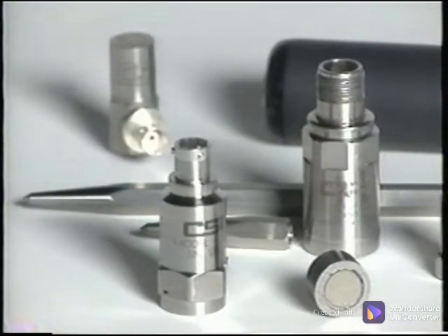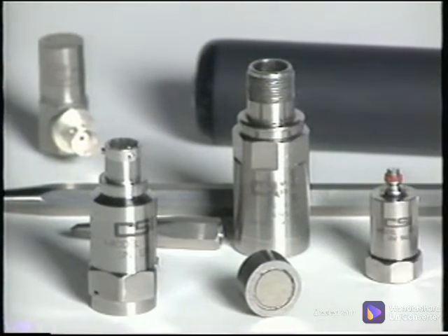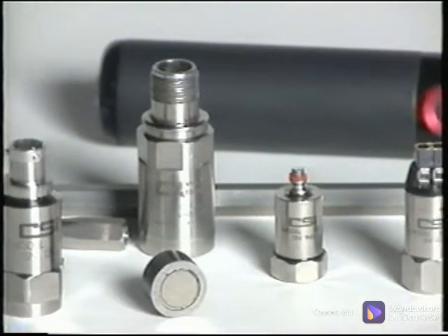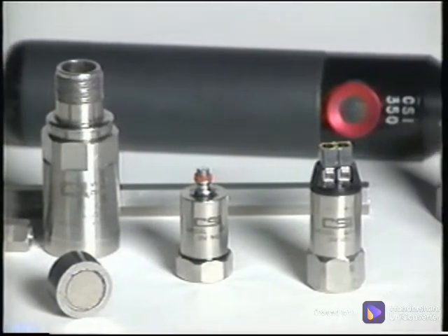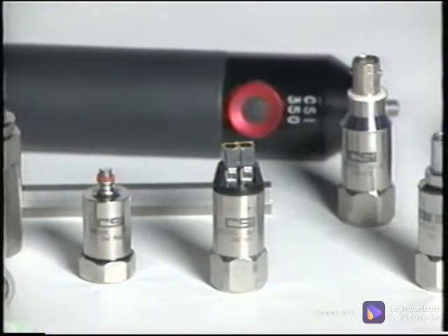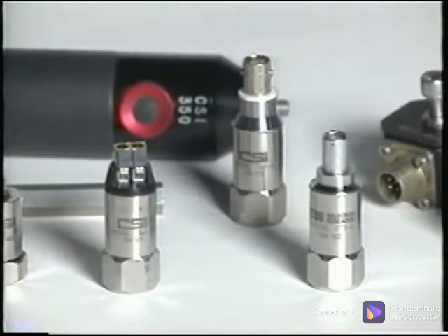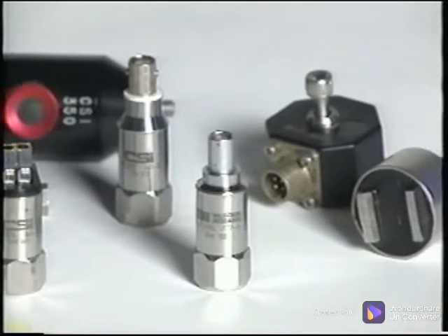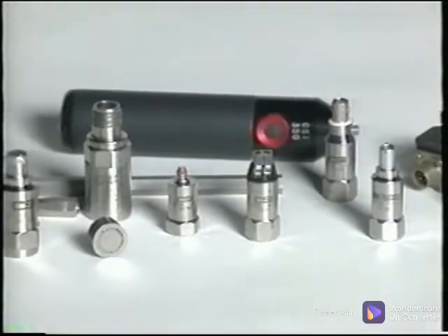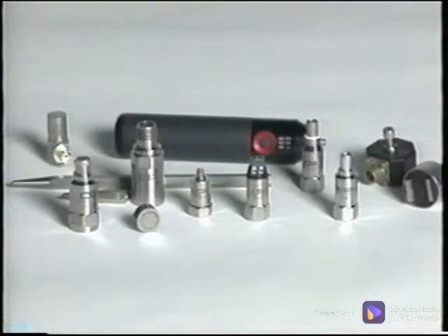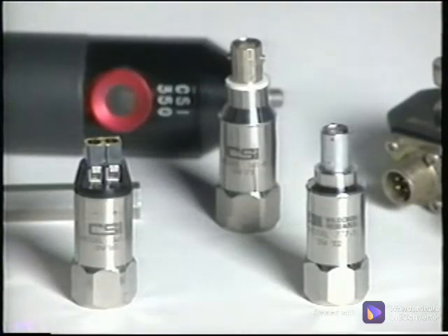In order to get the best data, we need to understand some facts and limitations of the various sensors. Each of these sensors or transducers has distinctive characteristics that may make it more desirable than another for a specific application. All of these transducers are either piezoelectric velocity transducers or accelerometers. Their size, sensitivity, and linear frequency range are the primary differences. Here, we will focus on accelerometers.